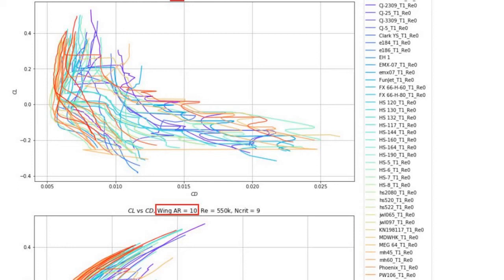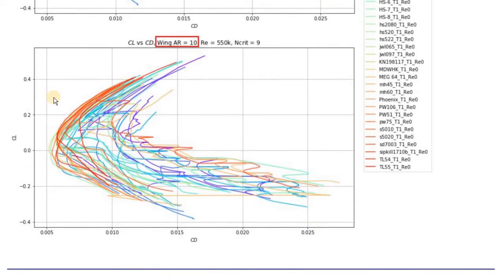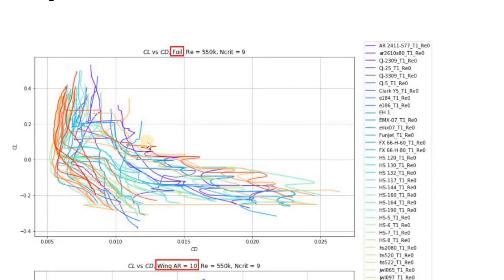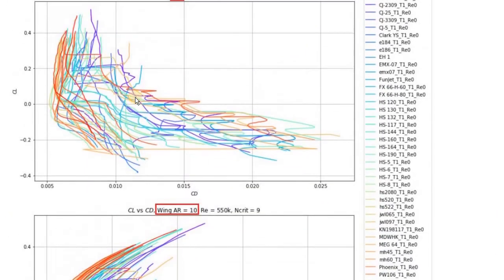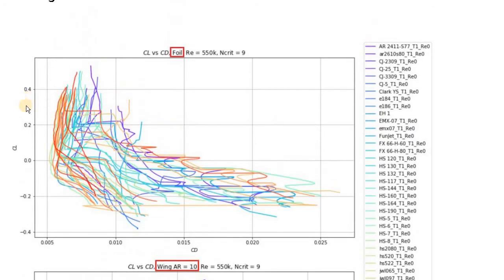And if you have this small number, it's going to be completely negligible, so we can ignore the wing. But if you would like to see a broader range of what's going to happen at high speed and high alpha, you can plot a bit more information, and then you're going to see those graphs. Okay, so once we have those curves, that's all we need, because we have the lift coefficient versus drag computed at low and high Reynolds number.